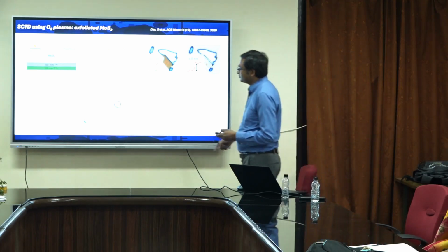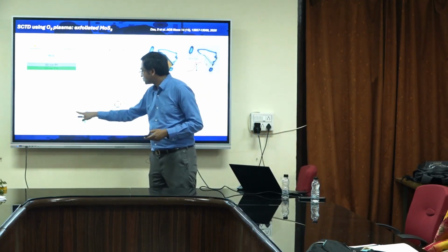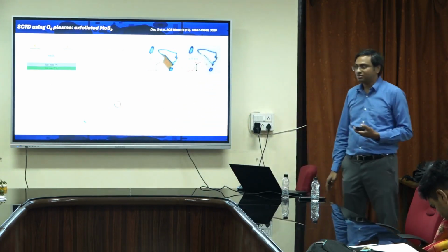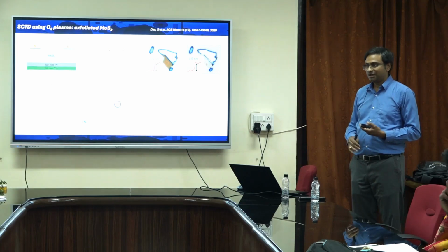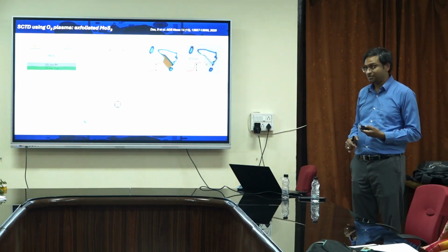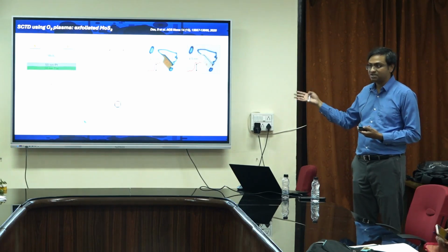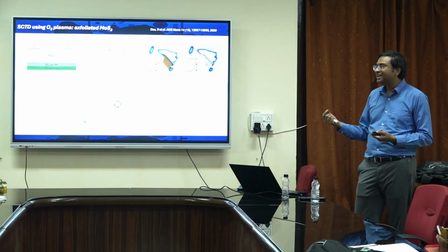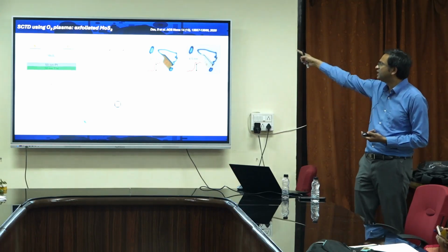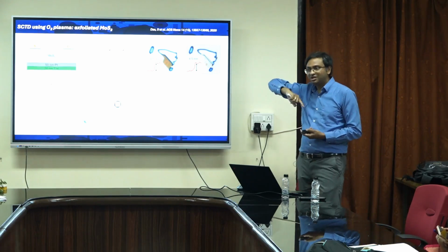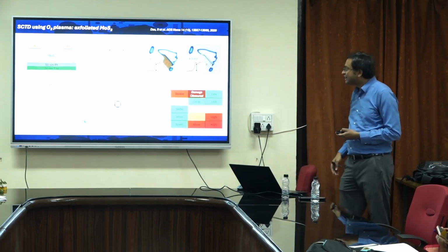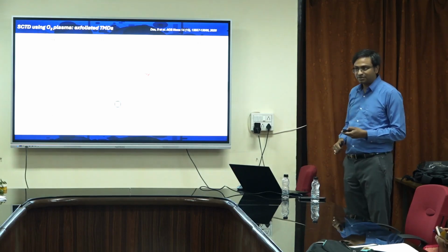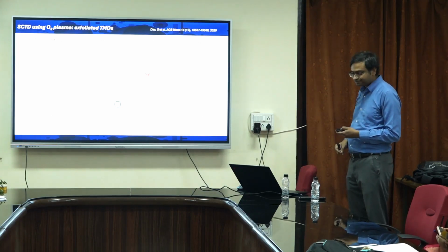You see, as I keep doping, some P branches show up. But the P branches are not very good. You see only a microamp current, and we were achieving 200 microamp for tungsten selenide, right? So even though we can do surface charge transfer doping, it's not the best approach for MoS2. We can only get so much good P-type characteristic. This is an older paper, 2020, and what I showed you earlier was more recent, right? But I just want to tell you that there are alternative ways of getting P-type material.